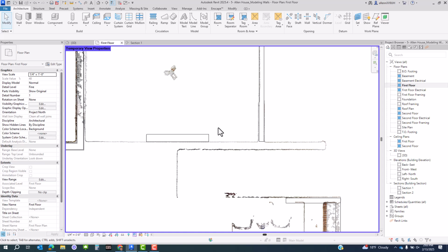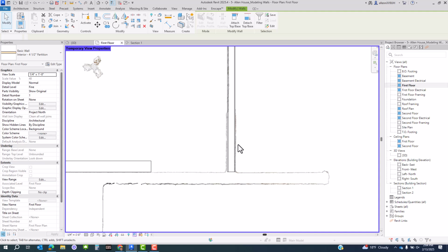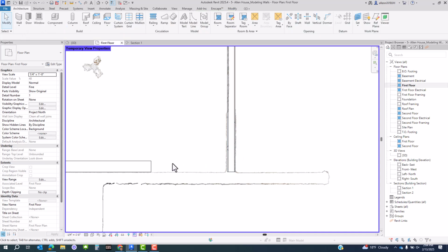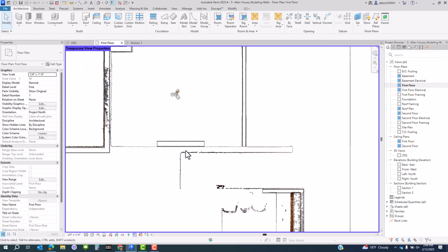You may have made the same mistake that I did, but all these interior walls, I didn't set them to the top of wall. And so I just need to go up to level top of wall. Then they'll run through my cut here when I'm at the high scan. Same with this one. I want to make sure that all the walls we place are set properly.